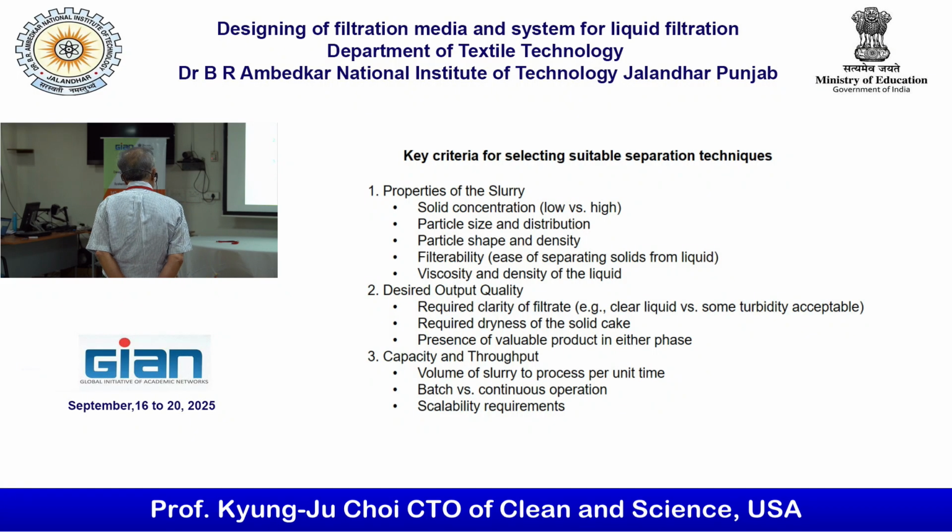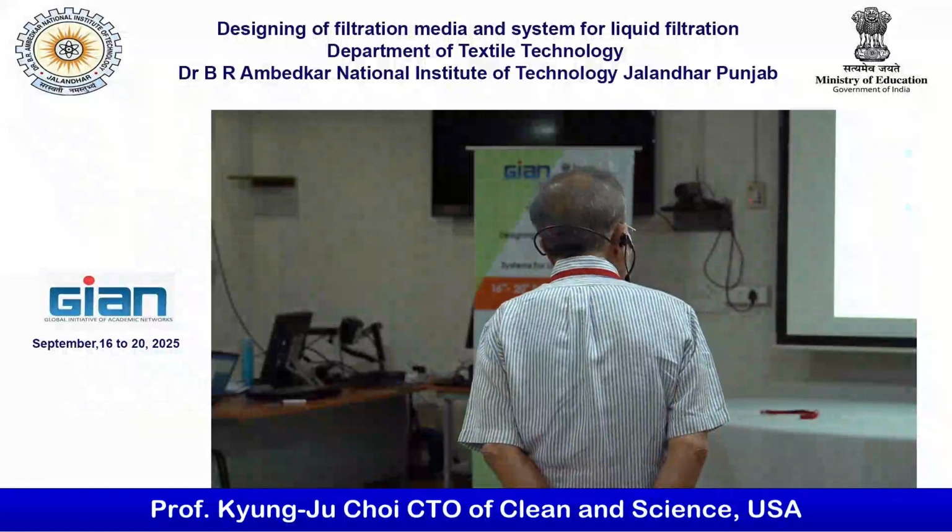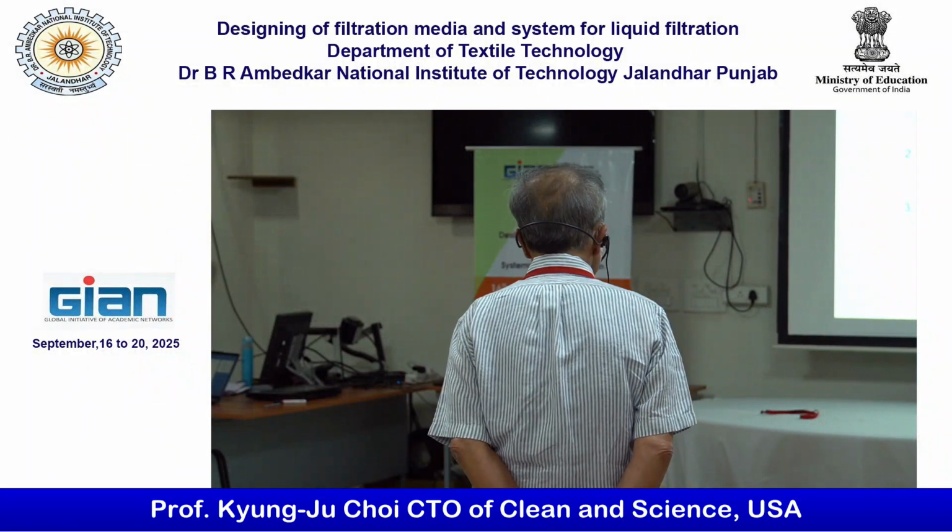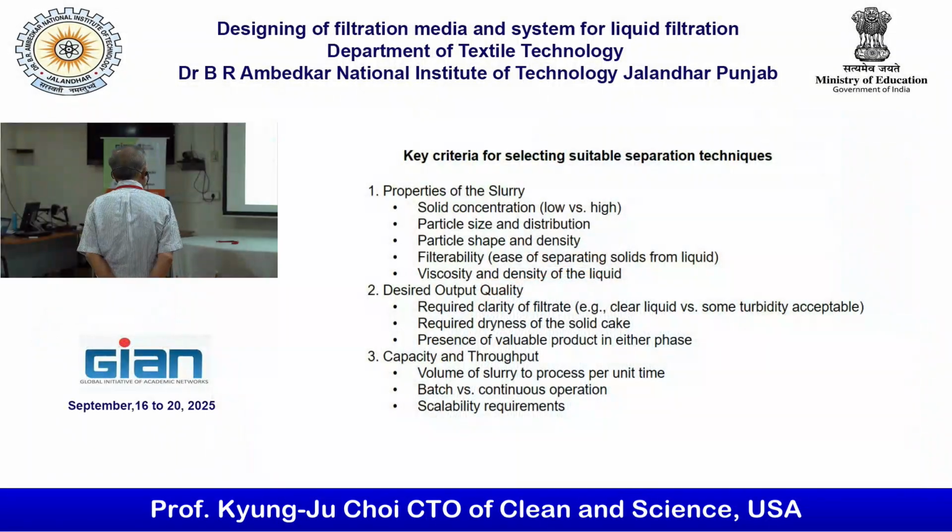Desired output quality: required clarity of filtrate, clear liquid or some turbidity acceptable, required dryness of solid cake, presence of valuable product in either phase. Capacity and throughput: volume of slurry to process per unit time, batch or continuous separation, scalability requirement.